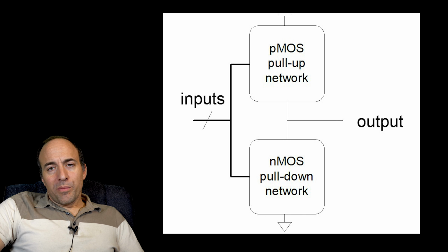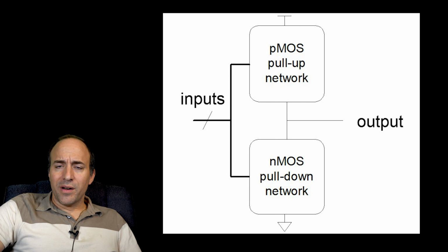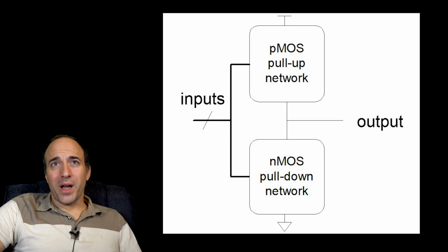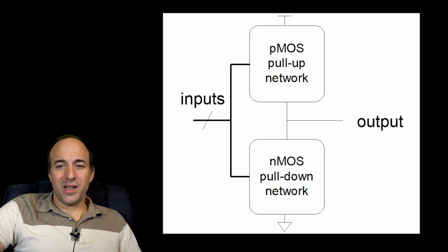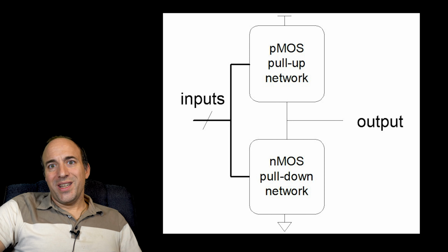So a little bit more specifically here, the P-type transistors will have one of their sides, and it's actually, the source and drain are sort of interchangeable, but the convention is that with the P-type transistor, the drain is connected directly or indirectly to the VDD.